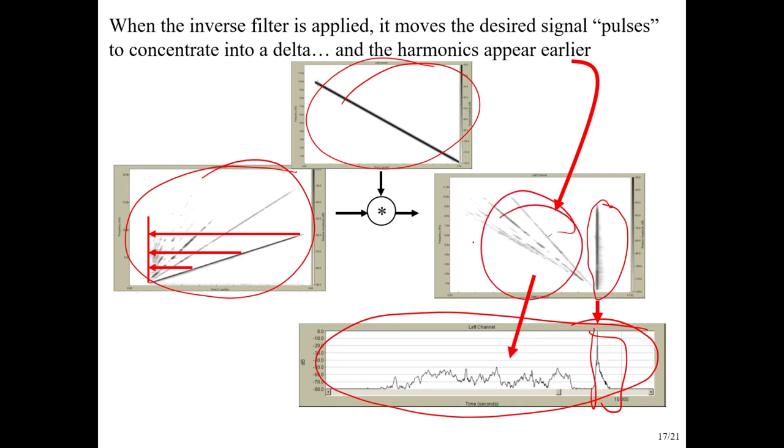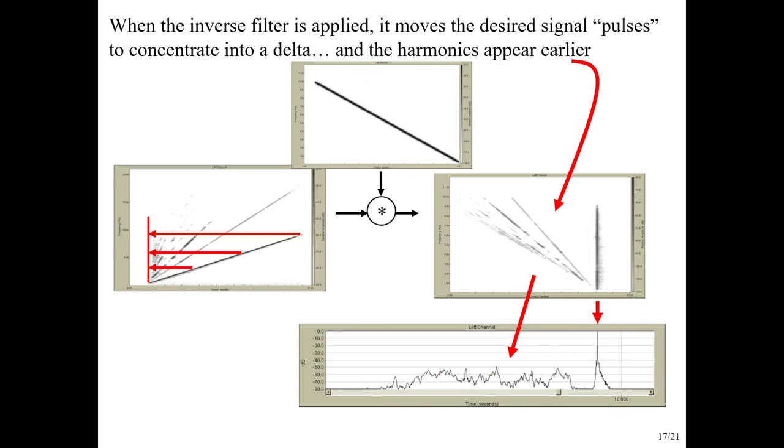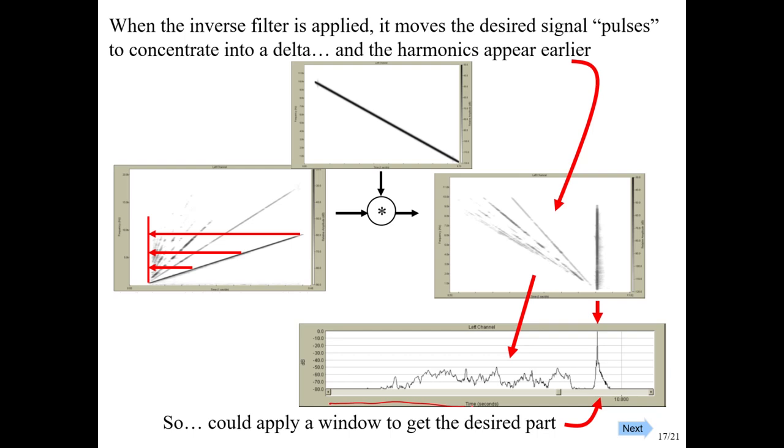And then all of this stuff is all down here, but it's all mixed together, right? So the nonlinear part is just pushed out of the way, has no effect. But we can't really tell what all those different nonlinear parts are doing because they're all on top of each other. But we can identify just the linear part. So remember, this is delayed, so we'd have to account for the amount of the delay. You can work that out if you're working through this. And then we would just keep from that point onward, just this part. That's going to be the impulse response of the linear part.